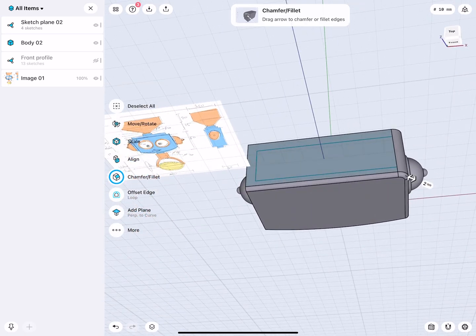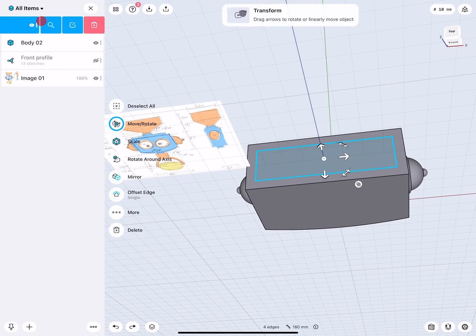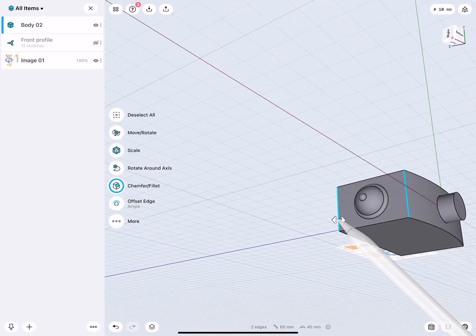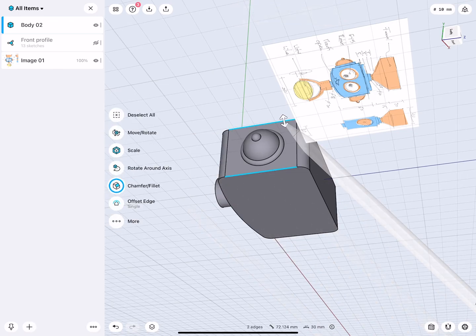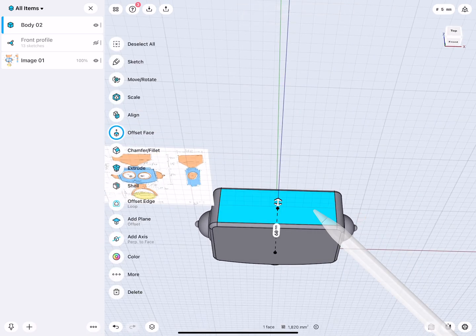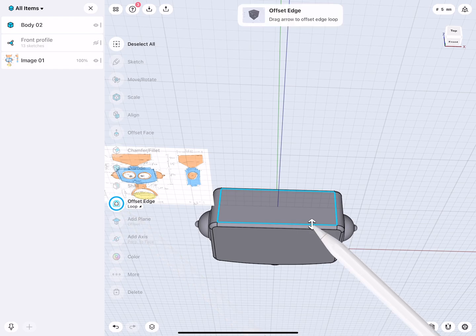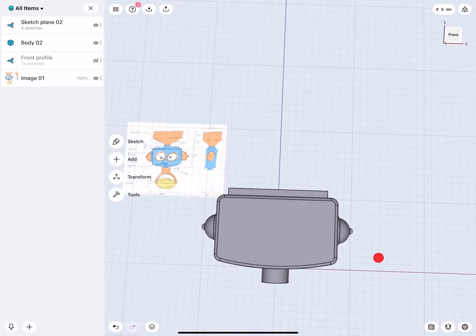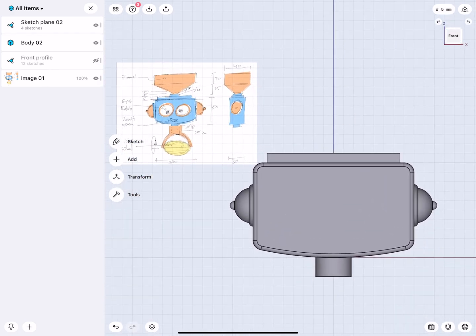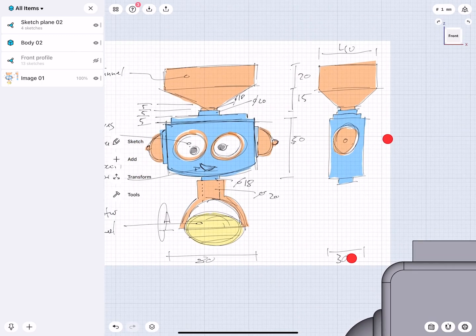Okay. Interesting. Now you see when I created the sketch, that actually created a problem. The sketch here I created on top of the face, I did too early. At this point, I have to go ahead and round these corners. Very nice. And then I round these corners. Good, because now I have a smaller surface. This one now I can more easily offset. I go by 2mm. All this can later be adjusted. And then we extrude this 5mm out. Very good. Cool. So we would like to have a 20mm socket on top.